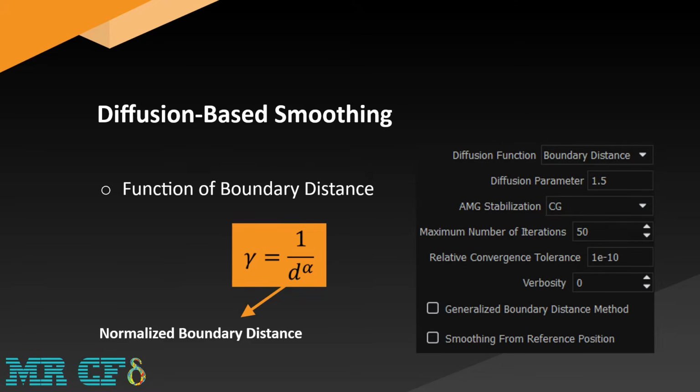Of course, this reduction in spread far from the moving boundary makes these areas, areas far from the moving boundary, absorb the movement of the mesh more. This means that these areas will change the quality of the mesh more than other places because less diffusion reaches them, while the areas closer to the moving boundary are better able to maintain their mesh quality because the diffusion is fully applied to them.